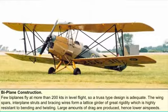Very few biplanes fly at more than 200 knots in level flight, so the air loads are low, which means that a truss-type design which is covered in fabric is satisfactory. The wing spars, interplane struts and bracing wires form a lattice girder of great rigidity, which is highly resistant to bending and twisting. Unfortunately, it also generates a relatively large amount of drag, which accounts for the fact that biplanes fly relatively slowly.